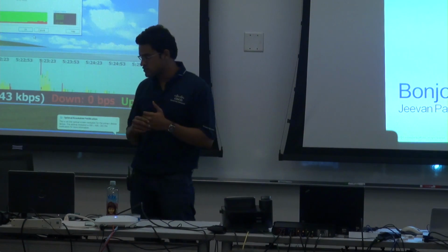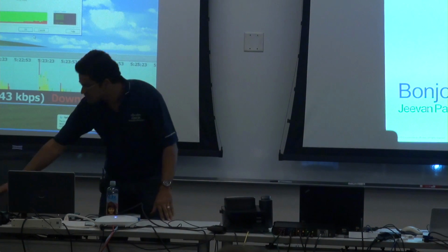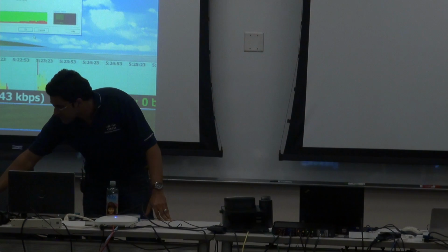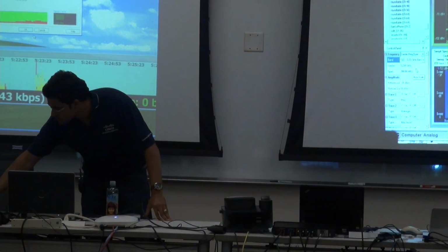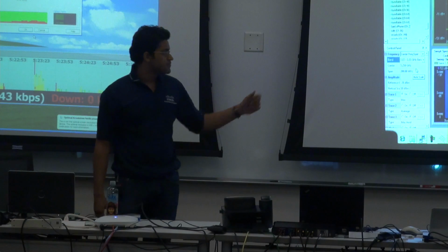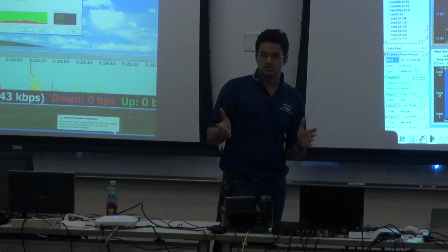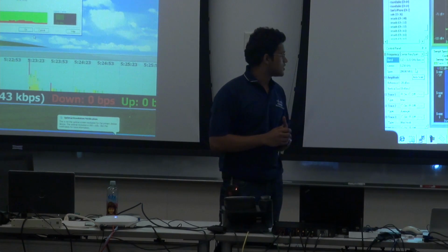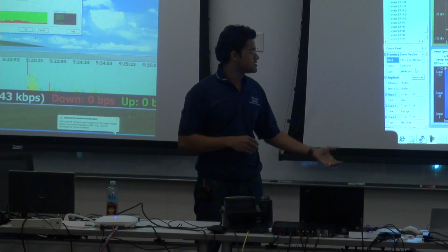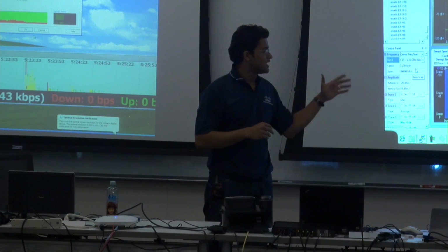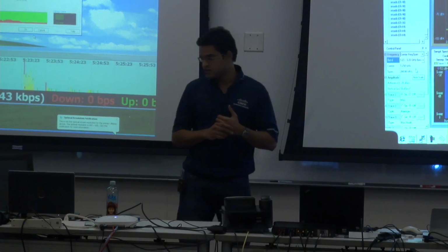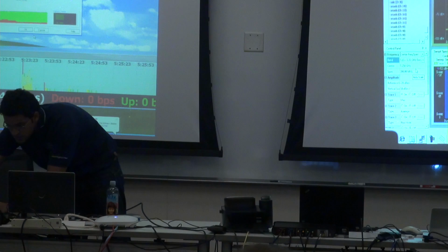What I'm going to do is just run traffic. So I have an XCA server over here, and we're looking at the spectrum out here. The primary channel that we're serving is channel 36, and what you're going to see is it occupying the 80 megahertz spectrum. So let me just start with the test.